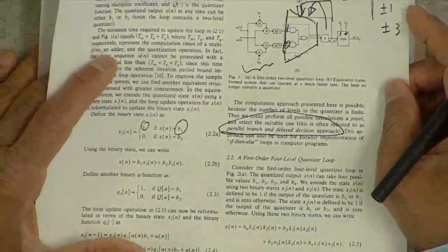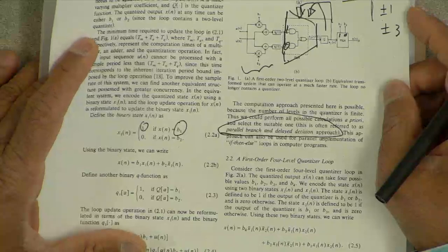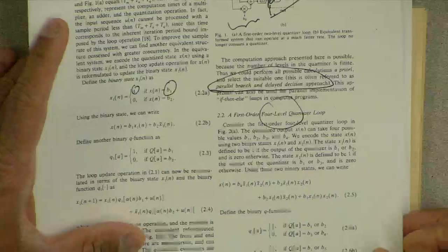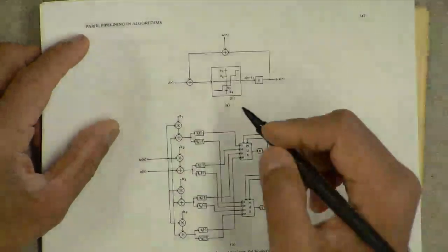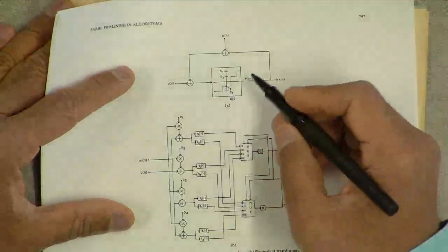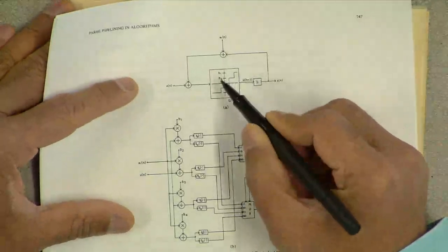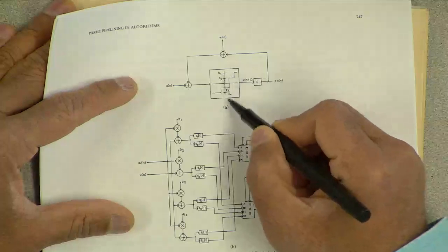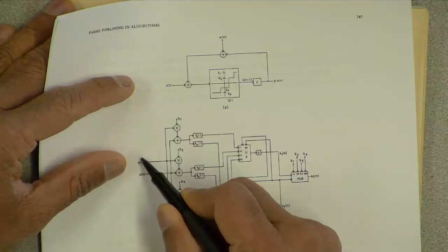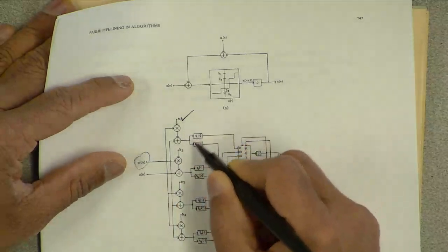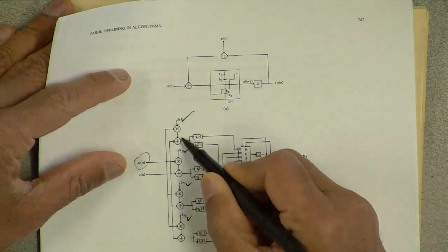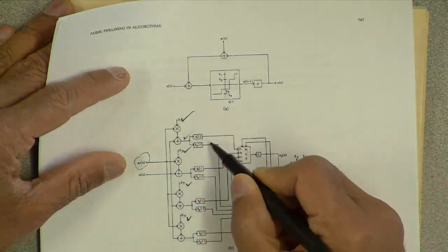There are more things in the paper, a couple of ideas here. What happens if the number of quantization levels is 4 instead of 2? So that's again very similar assumptions. If we have 4 levels, B1, B2, B3, B4, take the quantity alpha n, multiply by B1, B2, B3, B4, all of these, add them to the input U, and then quantize these.